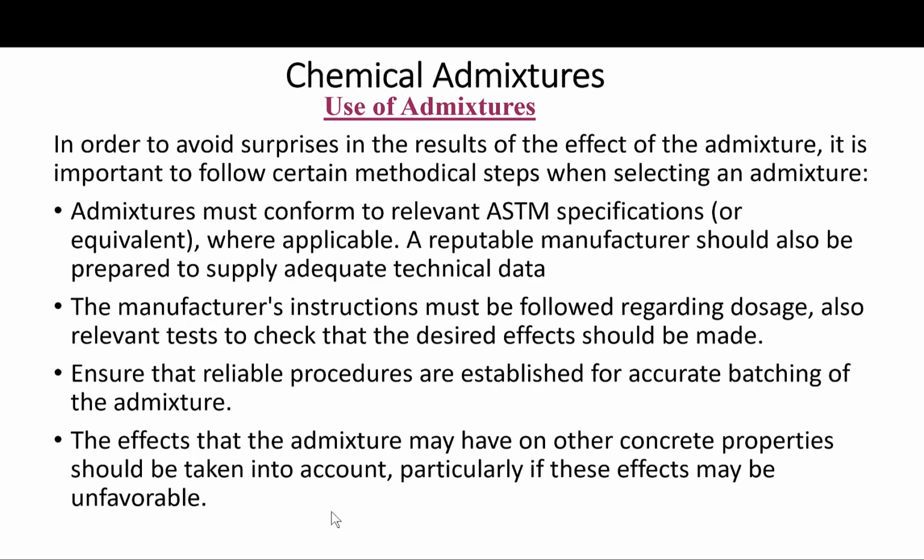Okay? Number 3, ensure that reliable procedures are established for accurate batching of the admixture. Again, this is particularly important for air entraining admixtures and all chemical admixtures, where typical dosages may be well below 0.1% by weight of cement.